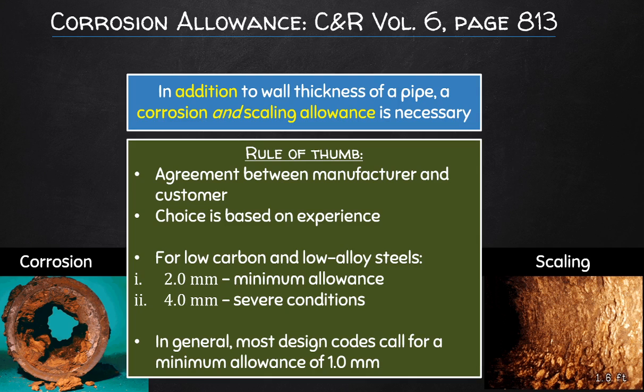So nonetheless, when working with steel pipe products, for example, it is best to select corrosion factors of between 2 and 4 millimeters, and in most cases you should at least plan for 1 millimeter. This is the bare minimum, but this is really playing with fire.